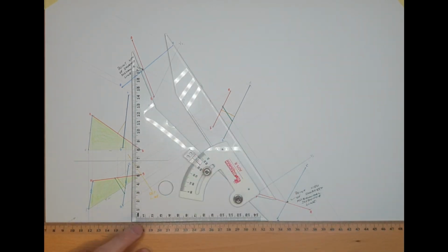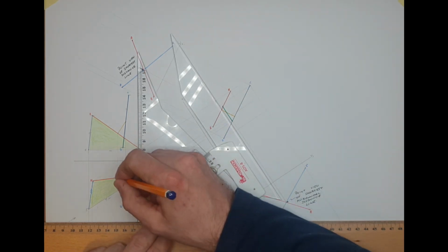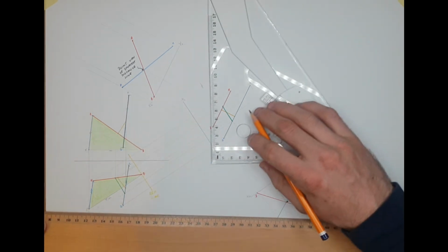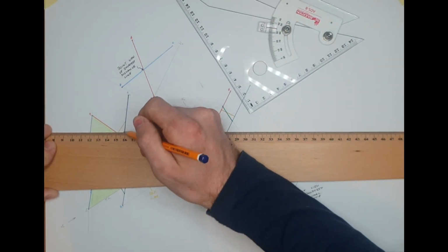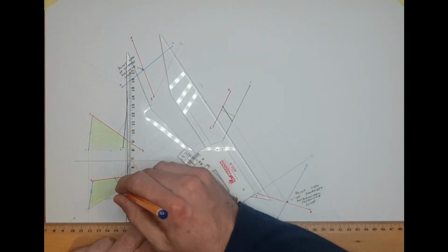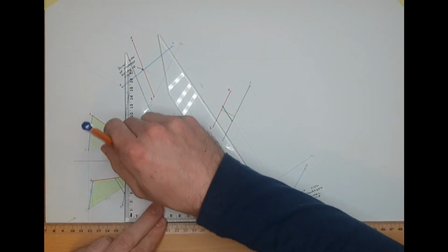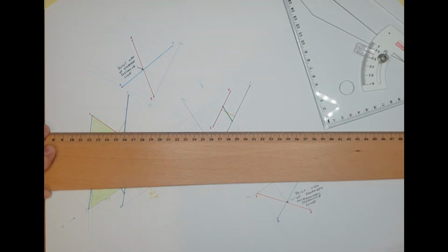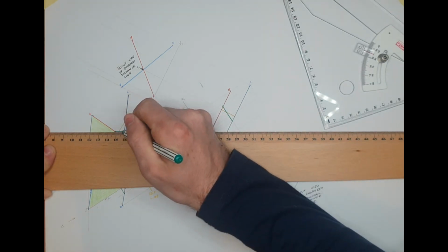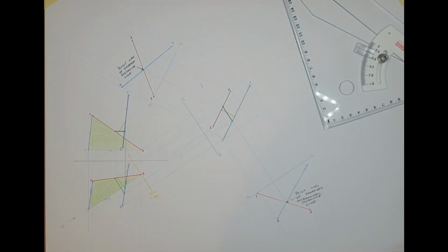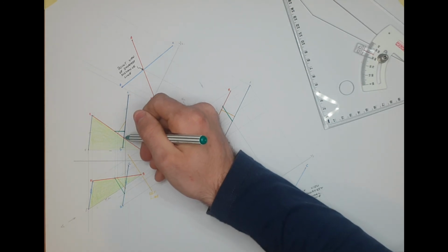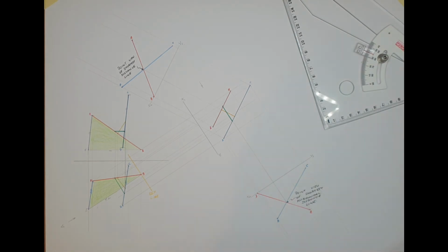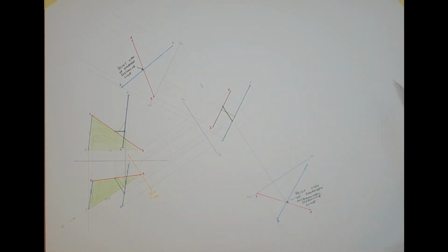I'll bring them up to elevation next. Into the green line and the red. Into the green line and the blue. We should find, just check that again just to make sure. Yeah. What we should find is that it's a horizontal line up here in elevation as well. If it's a horizontal line, it must be horizontal in every elevation. That's the point that's projected up from the blue there in plan and projected up from the red. So that's the shortest horizontal distance found.